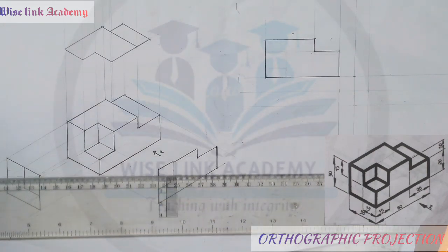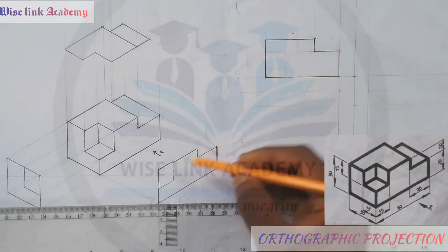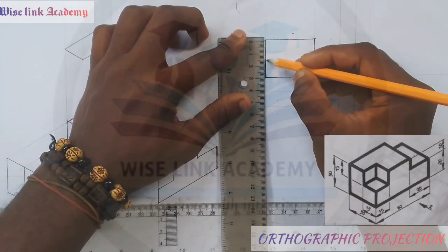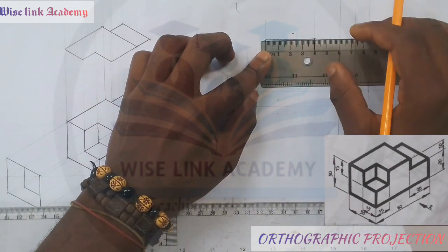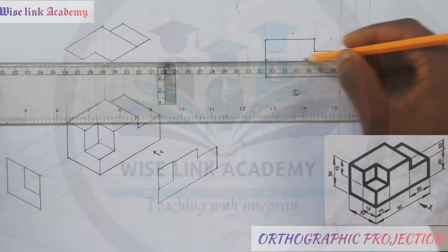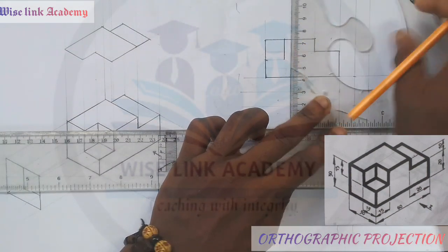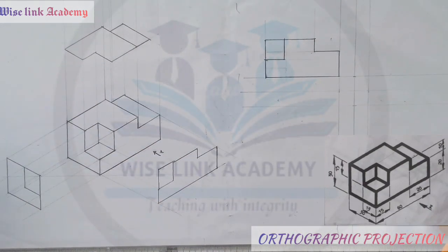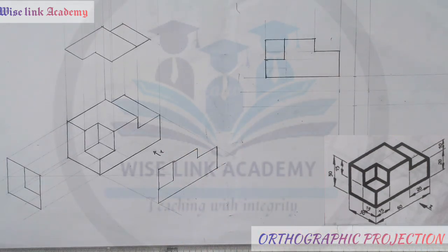I have this. My next task is that if you observe, there's a distance of 15. So measure 15 from here to here, which is this, right? Also 15 at this point here. I'll make sure those 2 points touch each other. The faint line inward, I'll touch that faint line this way. Also, I will close this part up this way. I have this, right? So this is what I've actually seen from my elevation. So this is our elevation.